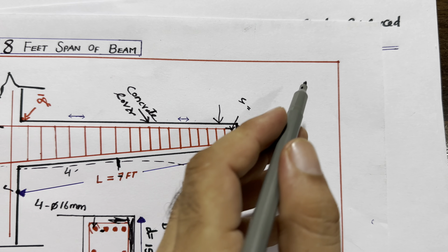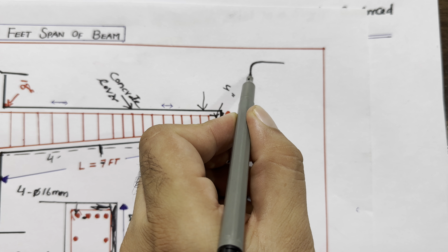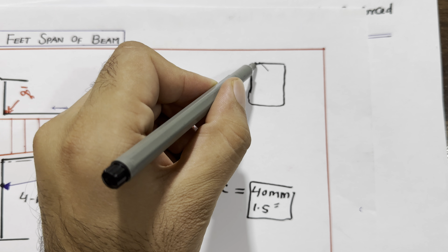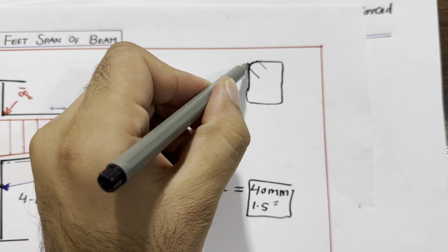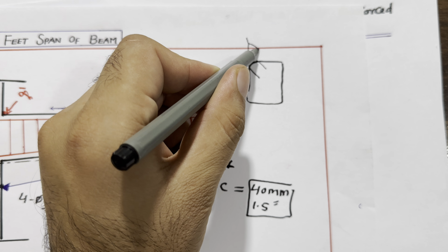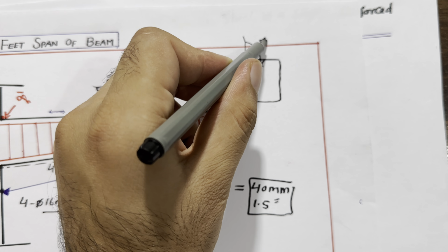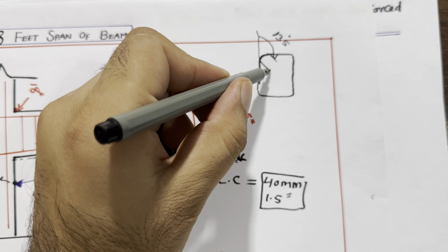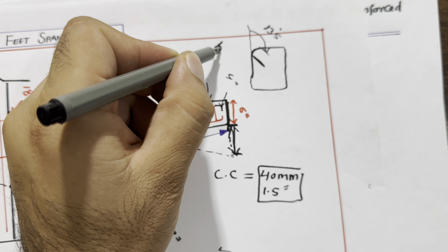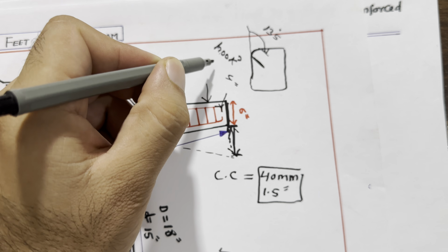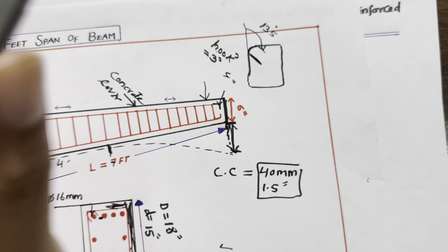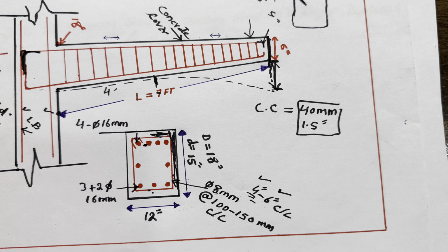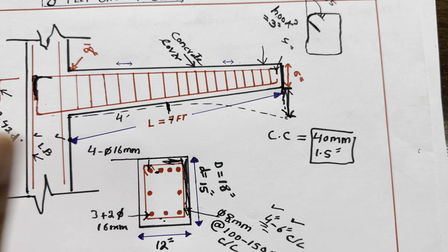Next guys, you can see, let me make the stirrup. So guys, you can see this stirrup is here, same like this. The stirrup hook should be bent at 135 degree. This is very important to know. This is 135 degree. Don't provide 90 degree. You will face more problems there. Next, if you see this length, guys, hook's length, hooks should not be less than 3 inches. This is minimum. As we discussed, the spacing and diameter, as I said before, 8 millimeter minimum you can use for this type of beam.